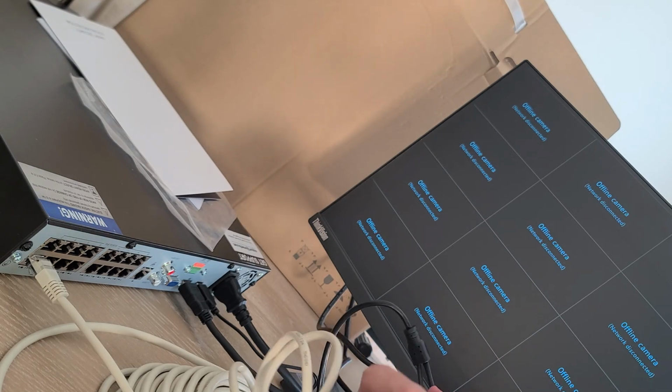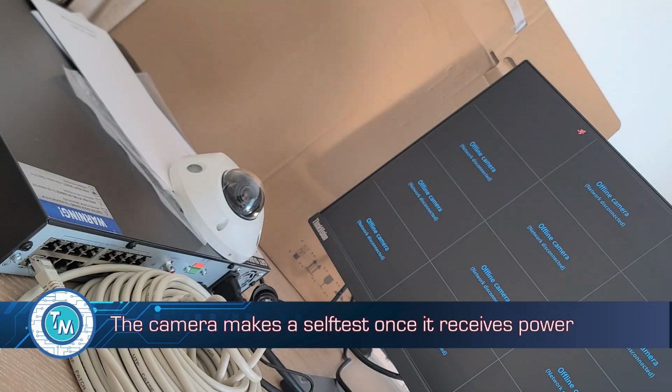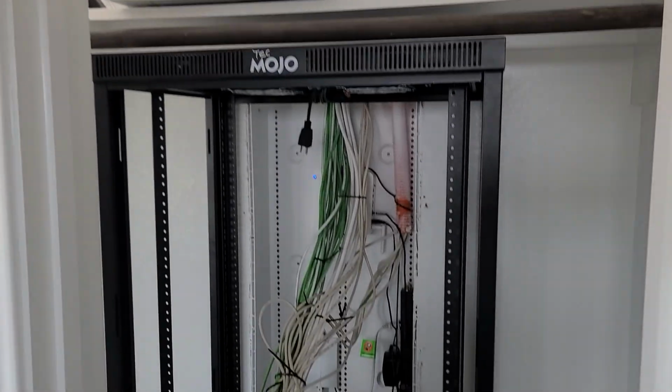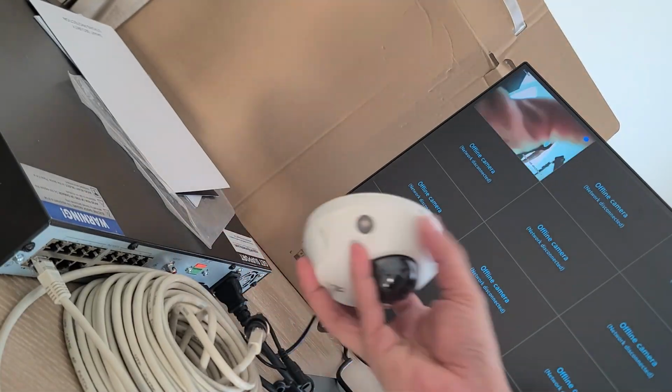At this point, all that we need to do is use the cables provided or that we installed to connect the cameras. Remember, we only need the data cable since it will also receive the power that the switch provides to each of the cameras through these ports of the NVR. In our case, we had a number of cables for network and cameras already pre-installed, but we ended up installing a good number of additional cables, at least for cameras, something that I see happens a lot.